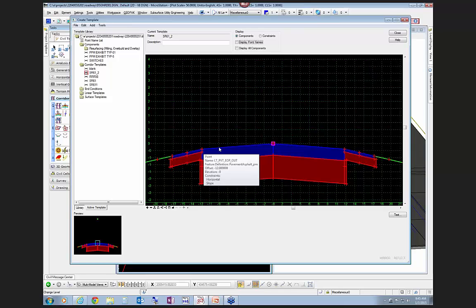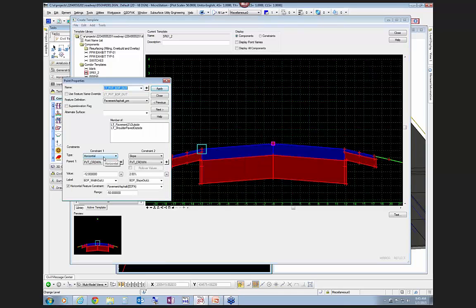If this existing roadway was 11 feet, then my corridor would stop at 12 feet, just because of the way that the override is. So what this is really saying is that this horizontal pavement width is going to be 12 feet unless a corridor reference has been added, which is this pavement asphalt. And if that has been added, then it will override this width to the width of the line, provided that it's from this location and 50 feet to the left of it.